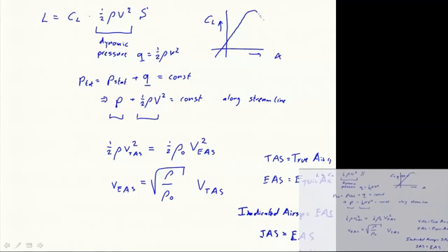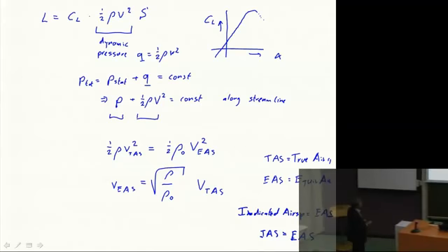That means that the lift force that we get is basically equal to this, which basically means that it would be the same if we would use the complete wing surface, which is now put horizontally, if we put that vertically and stop the flow with that wing surface, stop the flow completely, then that force that you would then get is the same as you get with the lift force when the CL is 1, which is a sort of figure close to a CL max.